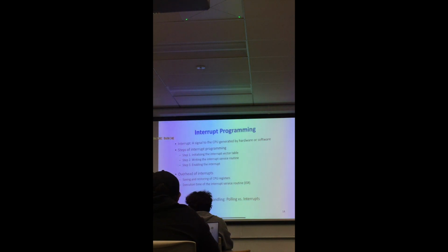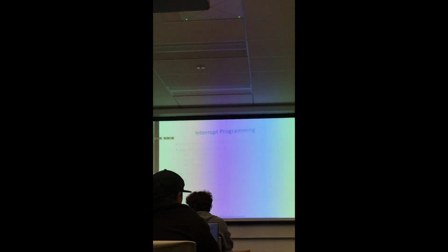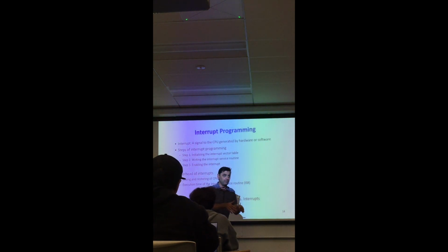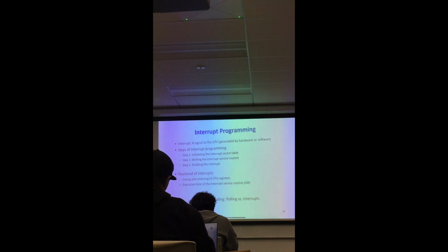So anyway, saving and restoring CPU registers takes place in RAM, which is the upper address of RAM. Stack is assigned to the highest possible memory. So if there's a memory, let's say, containing 256 bytes of RAM, the stack will start at address 255. And then it goes by loading the address, but it's still under the RAM, where the program and the data are located.